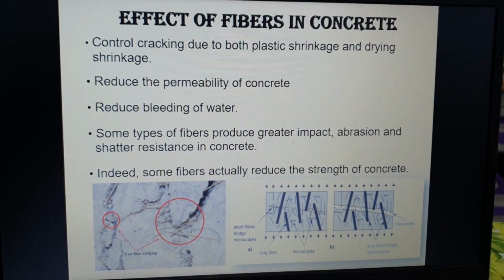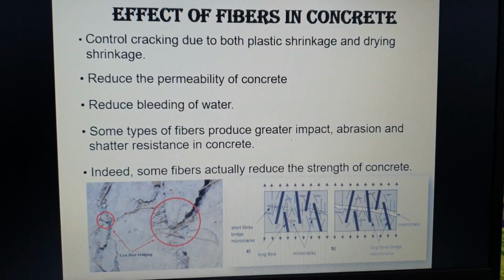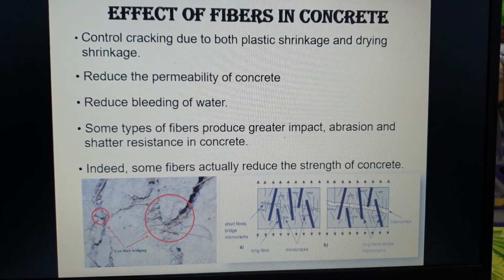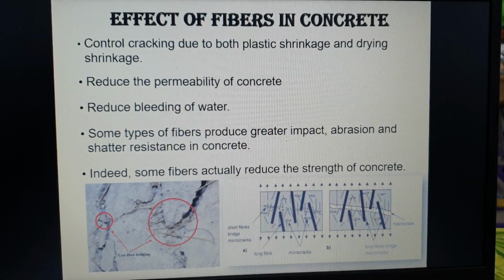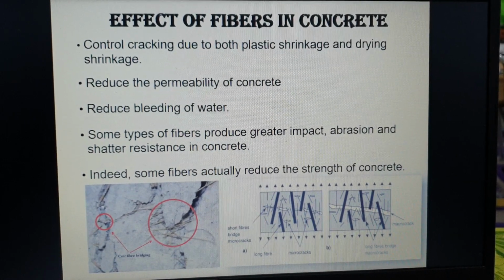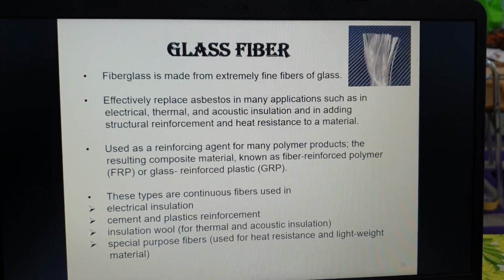Effects of fiber in concrete: it controls cracking due to both plastic shrinkage and drying shrinkage, reduces the permeability of concrete, and reduces bleeding of water. Some types of fiber produce greater impact, abrasion, and shatter resistance in concrete. Indeed, some fibers actually reduce the strength of concrete.